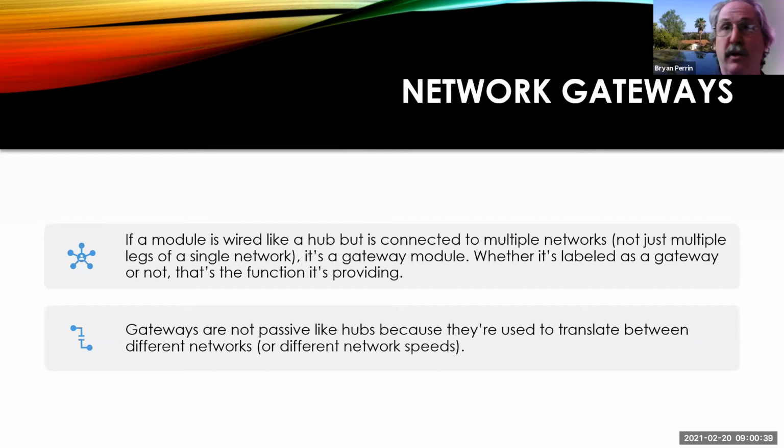As a matter of fact, the only module I'm talking to on the car, even though my scan tool shows 30 modules, is the gateway module. So if the gateway module goes bad, I'm talking to nobody. Even though the car may still start and run, I have a lot of lights on in the dash, but I can't talk to anybody.